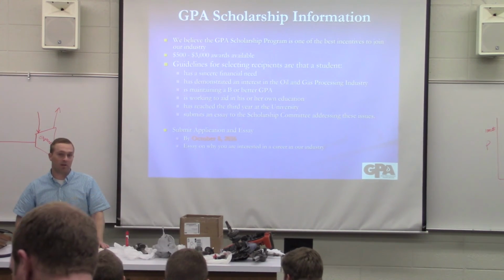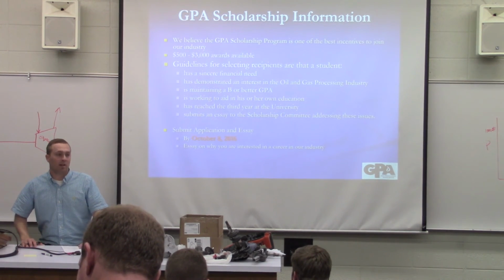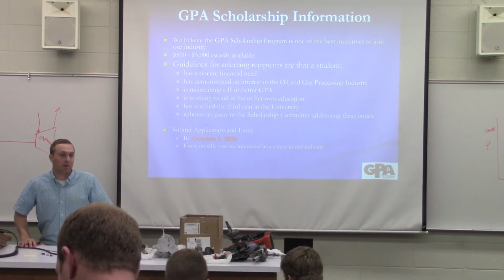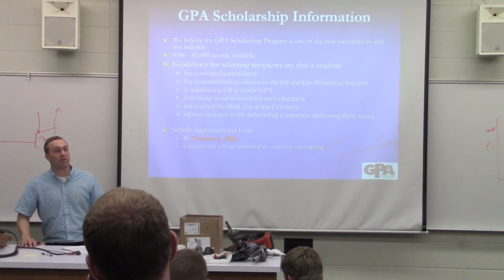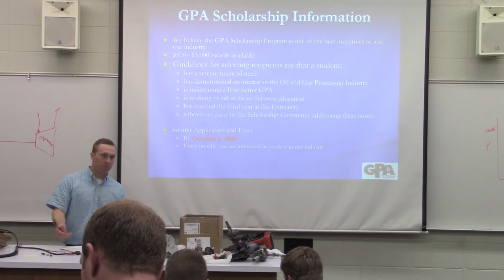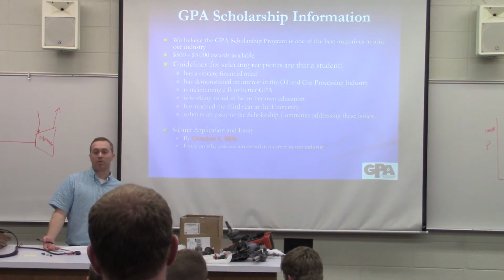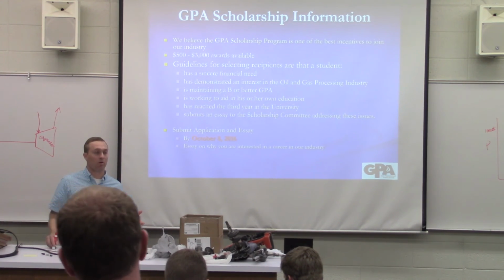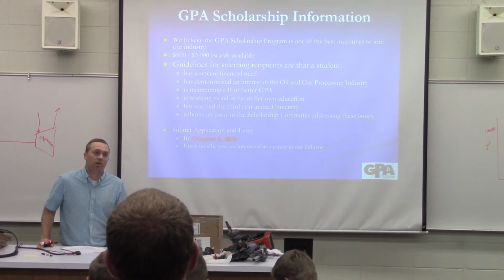There's a lot of safety in our industry, which, don't be turned off by that. Safety is very technical and challenging as well. It's not just about telling people to wear steel-toed shoes and hard hats. There's a lot of process safety that's really interesting. In our processing plants, OSHA mandates that we do process hazard analyses every 5 years, and it's a pretty tedious process, but you go through and evaluate every part of your plant and look for what could fail.